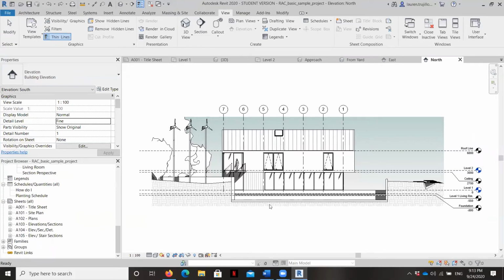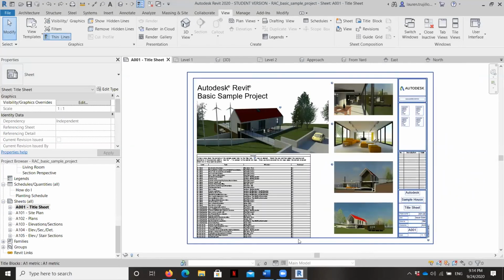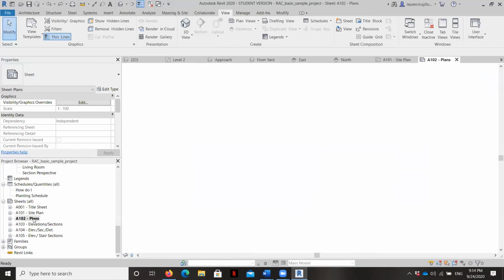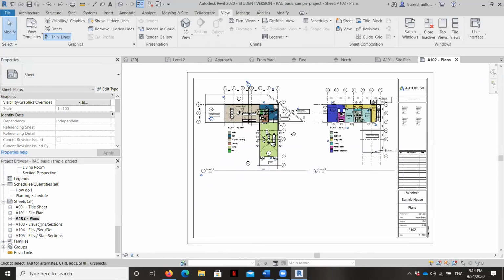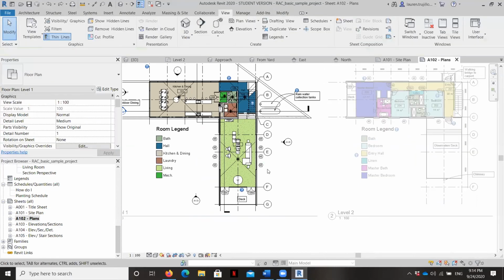Once all of these different things, which are called views, are created, then you drag them onto sheets. And so you can see here, there's a sheet section, and there are different views and different objects on each sheet. If I double click in here, you could think of this like a viewport in AutoCAD. And again, we're going to spend a lot of time making these, so I don't expect you to retain anything as far as the technicalities of how you make these things,